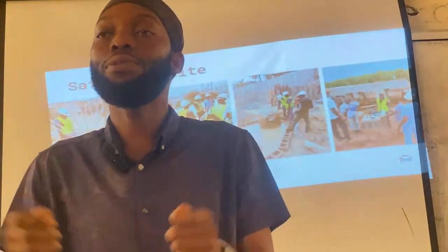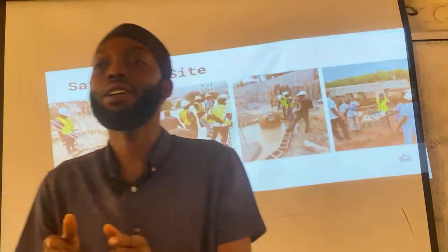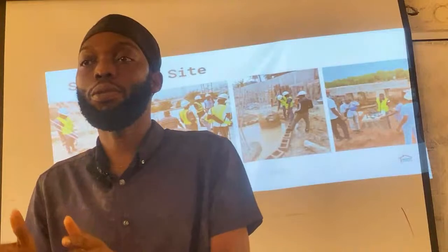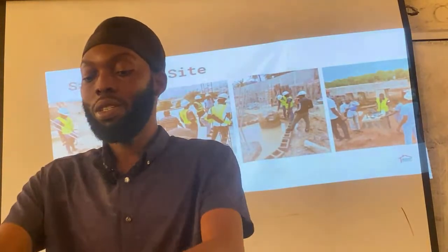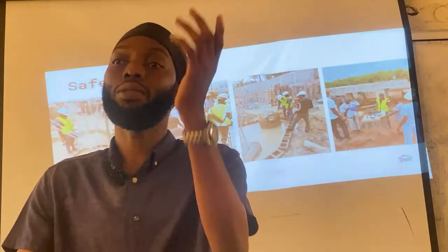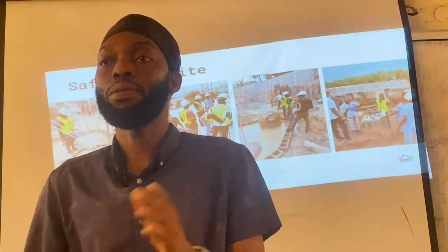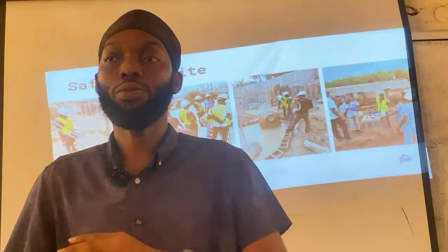So the only thing you can do right there, even if it does not show signs of crack or any other thing, just that the values it's showing are not good, you call your structural engineer, who prescribes solutions to mitigate that particular issue. Probably, if it's on the ground floor, you break the foundation beside that column and erect another one, the jacket, whatever.